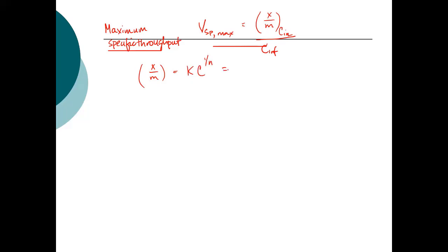So we'll use data for microcystin. That would be 59.9 times 1.0 milligrams per liter to the 0.48. This would have to be provided for you on the homework problem. The Freundlich parameters are provided.